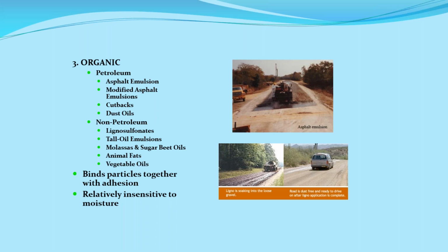I only have two different agencies in the western states that use the sodium chloride, because of the same problem. Here in the western states, our humidities, when we talk about humidity, we're talking about 8, 9, maybe 10% during the summer. And so we're really low humidities compared to Michigan. And so the sodium chloride, I really don't recommend it as a stabilizer because of that issue.